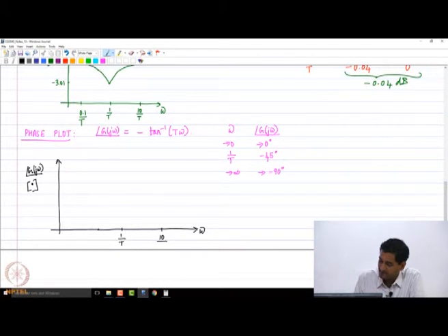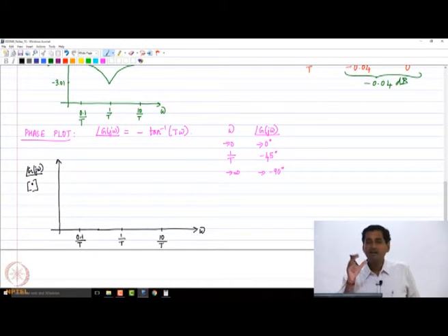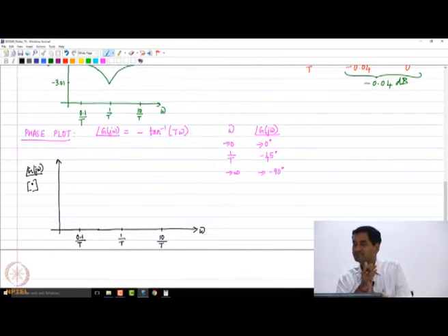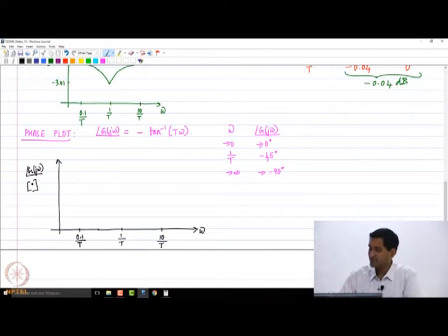Let's say I take 10 by capital T and 0.1 by capital T. Typically in most Bode plots, we plot around the frequency range of interest, and by and large you choose a frequency range and go 1 or 2 decades either side. That covers a pretty broad range. So that's why I am taking 1 decade above and 1 decade below a particular frequency.